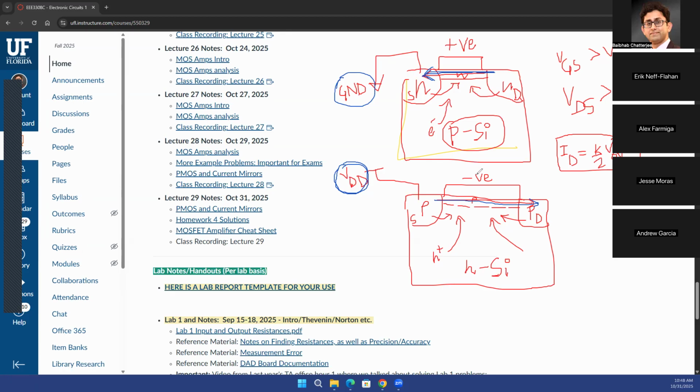So the negative voltage that we talked about at the gate, that really means that you have a negative VGS, right? You have a negative VGS for the PMOS. This is the PMOS, where you wanted to apply a negative voltage at the gate. That means you have a negative VGS. And that also makes sense, right? Because the source is connected to the highest potential of the circuit, which is VDD. So now you apply something that is smaller than that. Of course, the highest potential of the circuit is the highest potential of the circuit. Anything else that you apply at the gate will be at a lower potential. And if that happens, your gate to source voltage is going to be negative, right? It was positive for the NMOS, it is going to be negative for the PMOS.